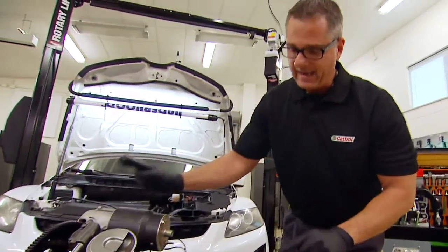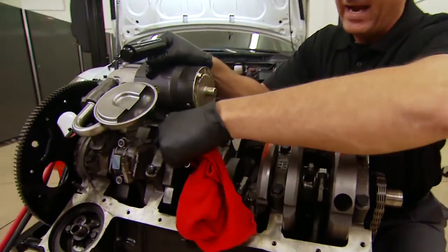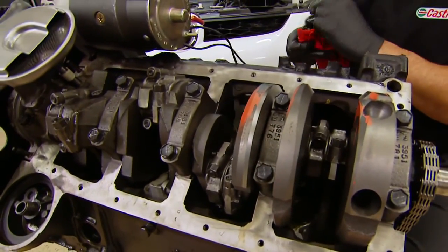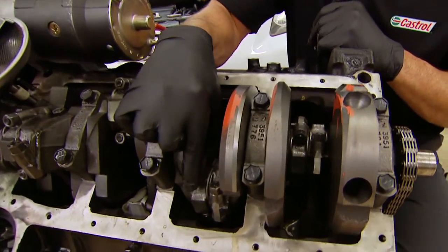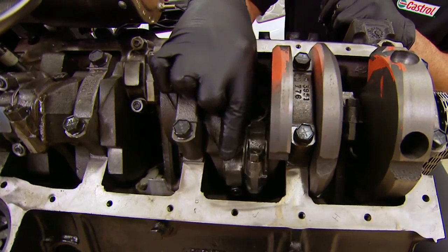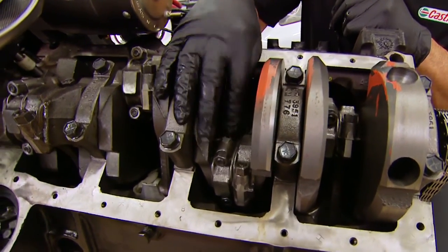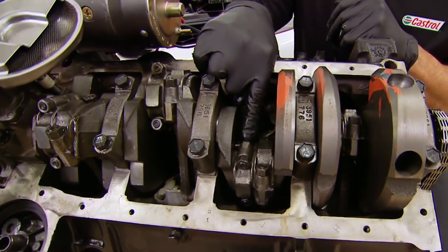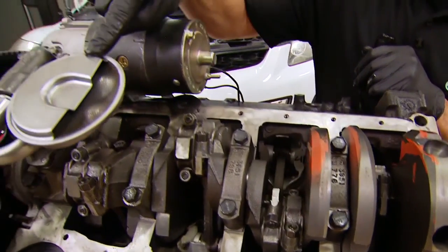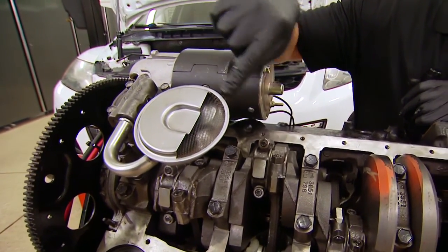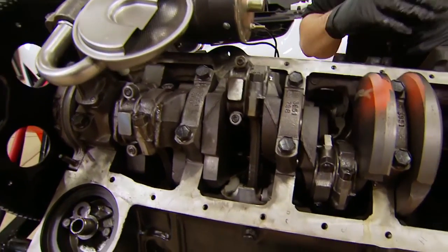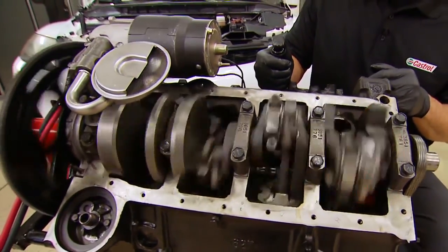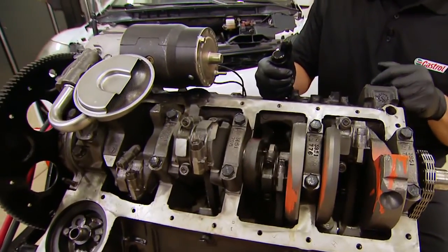Now, down here what we have is we actually have the crankshaft. The crankshaft goes completely down the engine, and you can see here some main bearings, and then there's some connecting rod bearings right here. So what happens when I spin this over, this crankshaft's going to run, the main bearings are going to spin with a film of oil, the connecting rod bearings are all going to spin with a film of oil, and then it all starts right here with the oil pump. The oil pump's going to go ahead and pressurize it, take it through the oil filter, and run it through all the oil galleries. So if I spin this one over down here, you can see everything moving.